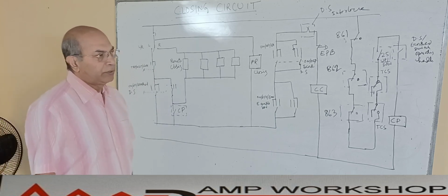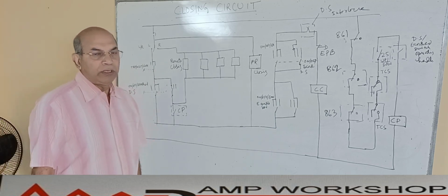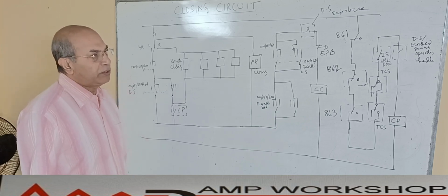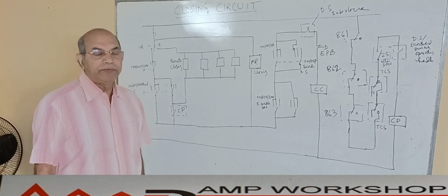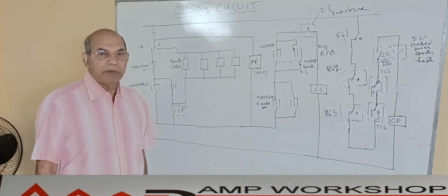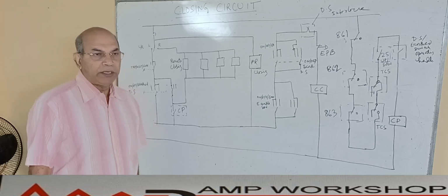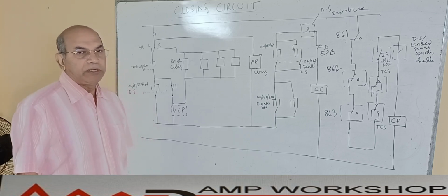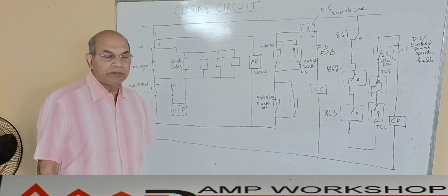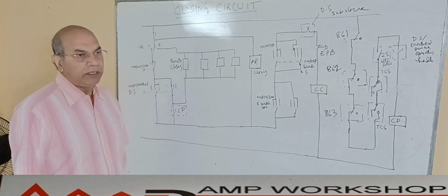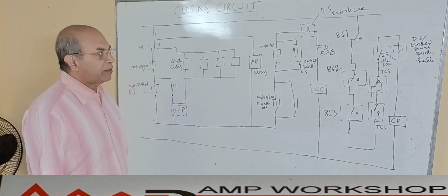Just to recall the previous discussion, session 1 of workshop 8, where we discussed the busbar arrangement and the breaker and the other power devices required for the switchgear. We have seen that in the case of a circuit breaker in the fixed type design, we need an isolator on the bus side.